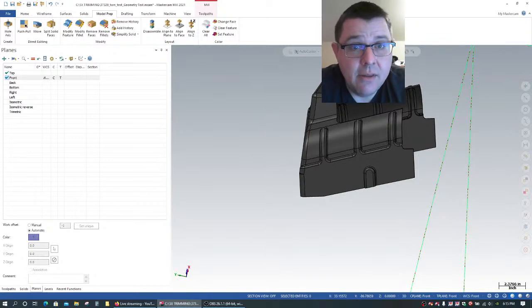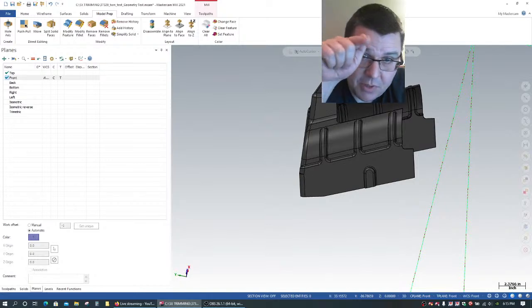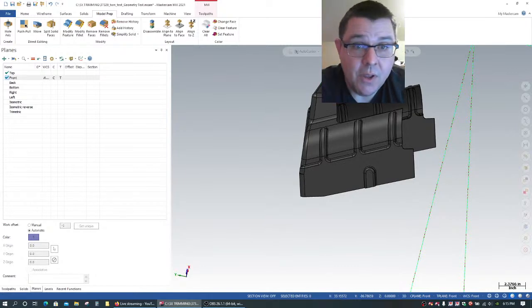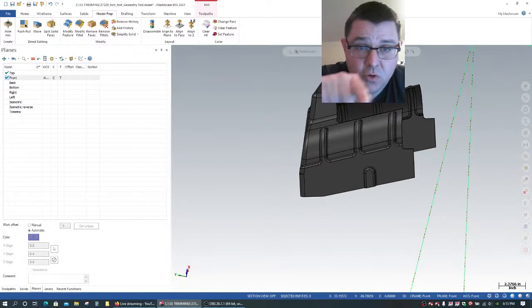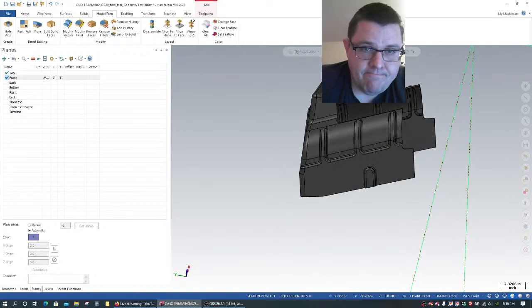Maybe it's just the same operation, right? I just picked up and I just did one cut. Now I'm going to reposition my tool and I'm going to make the next cut, and then I'm going to reposition my tool again and make another cut, but it's all part of the same op. So I don't want to change rotations. I just want to move the tool tip in XYZ, if you will, but without rotating AC or BC or any of that.